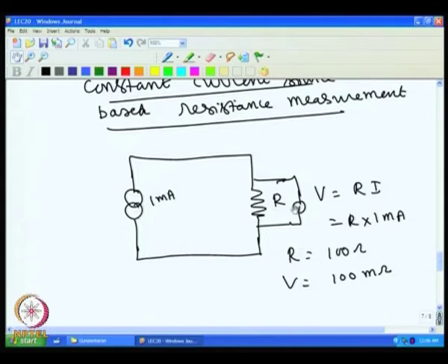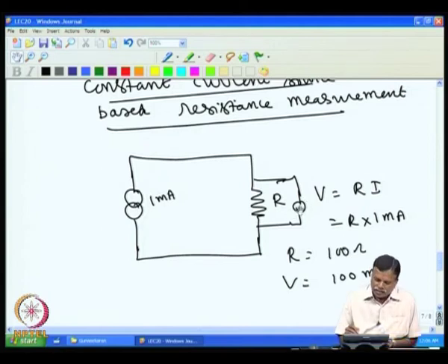Similarly, we will have a voltmeter which has no error, and the voltmeter also drifts with temperature. So, temperature will play a very significant error, and then the usual calibration error, because what you have set as 1 milliampere may not be correctly 1 milliampere, even if it is not changing with temperature; the 1 milliampere may be estimated wrongly. Similarly, the voltmeter also will have a calibration error.